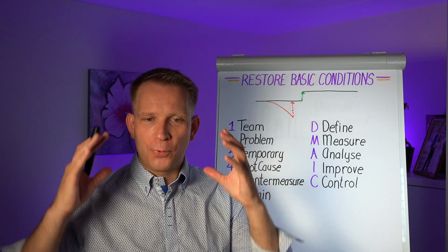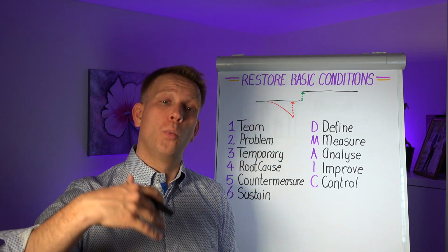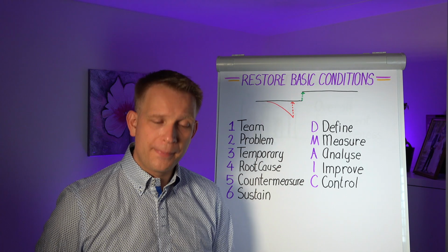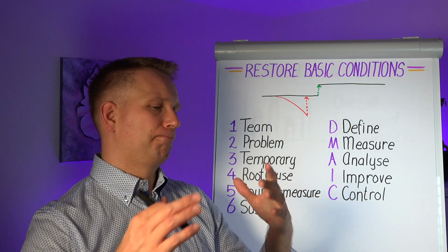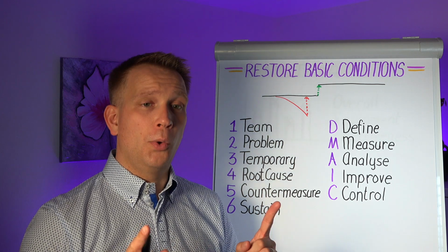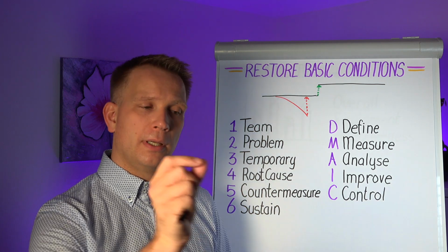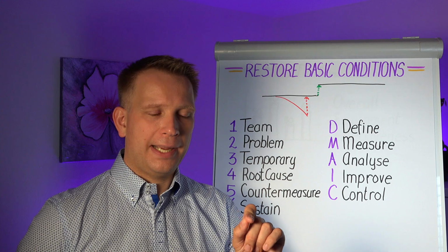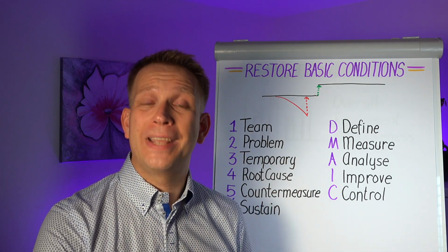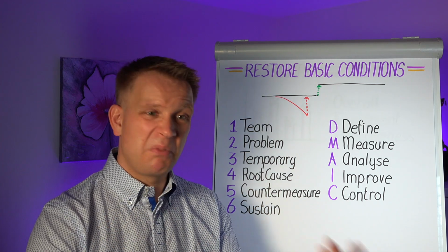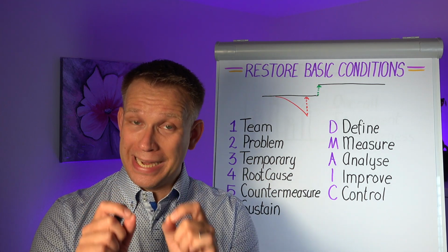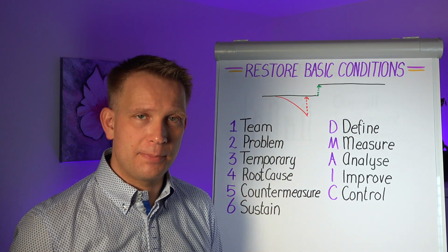This is process knowledge that you want to build up when you are doing your improvements, your process design, your general performance control. When we see the problem of it's starting to cut into the right side of the product, oh, that is usually linked to that roller, this connector, or that knife not being sharp enough. Let's check those 3 things first before we do anything else, because 80-90% of the time it's one of those 3. That is what you need to build up. It's not in these systems.